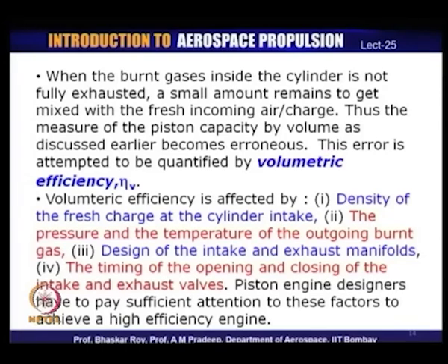As a result, effectively the piston capacity, the volume with which you have been working, gets reduced. This error is now quantified through a term which we call volumetric efficiency.